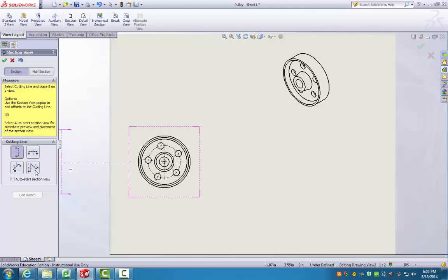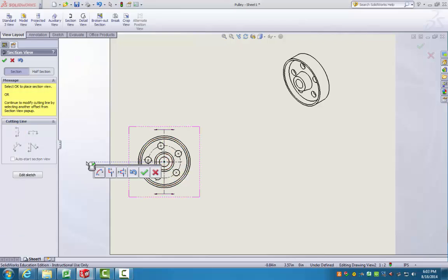multiple line section view. So what we want is we're just going to do vertical, and we want to make sure it's the center line, the center point, and it pierces straight through the center. So I'm just going to make sure that I click the center of the circle. And we're happy with this. We don't want to do anything crazy or fancy. This would be if you wanted to create a notch, say if I wanted to notch around so it didn't include part of this circle, or do single offsets and so on and so forth. Again, for more information about when you would use any of these, I would point you back to read carefully the beginning of this chapter where it describes the several uses of section views. So I'm just going to hit OK.